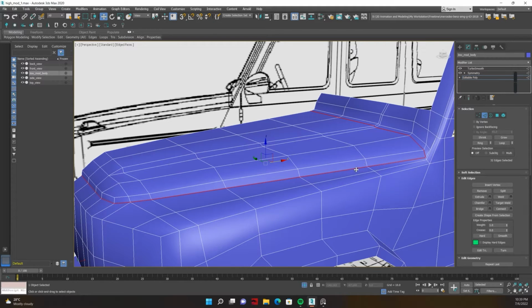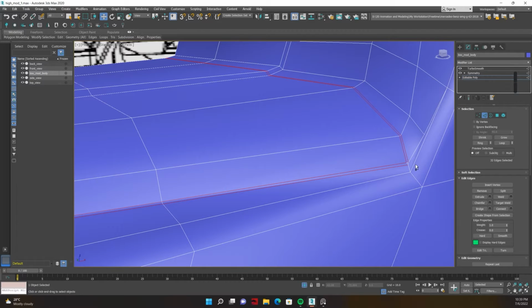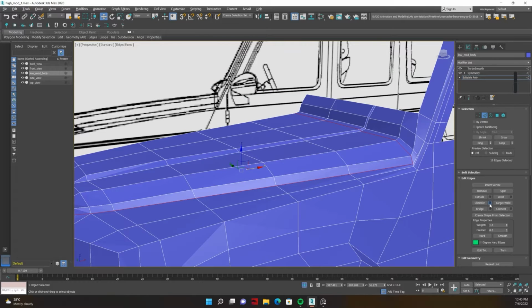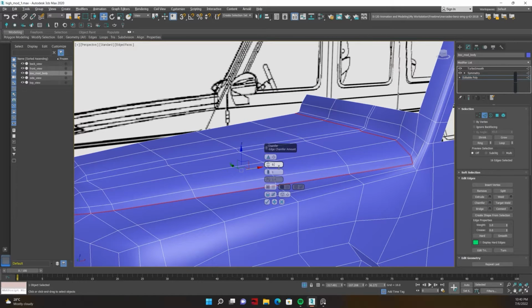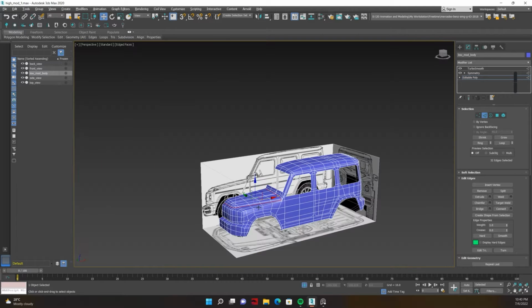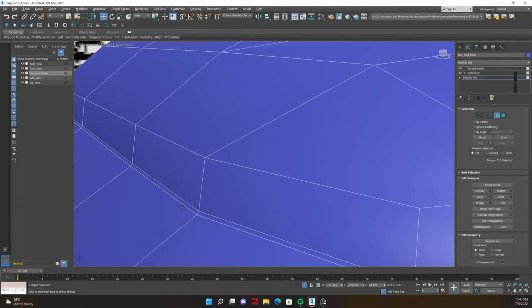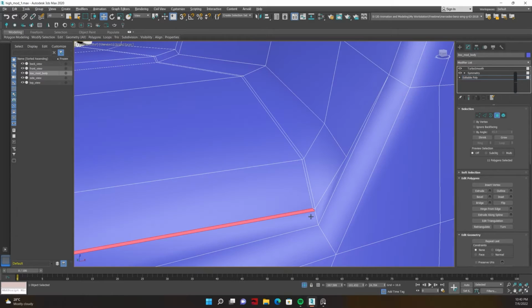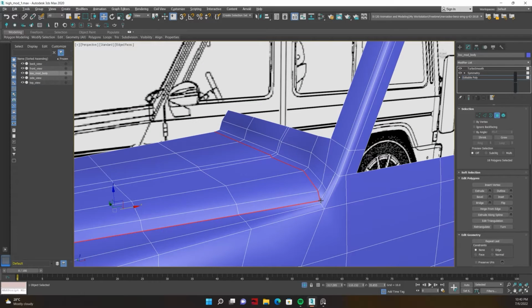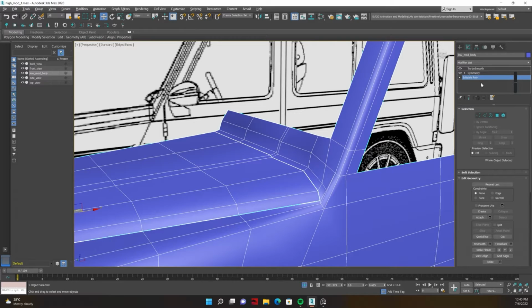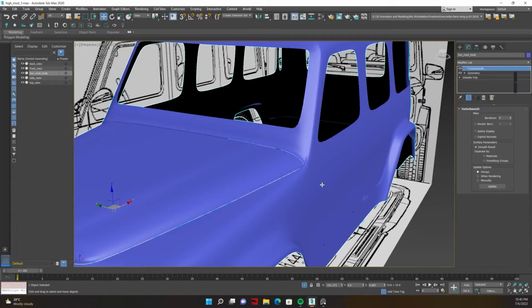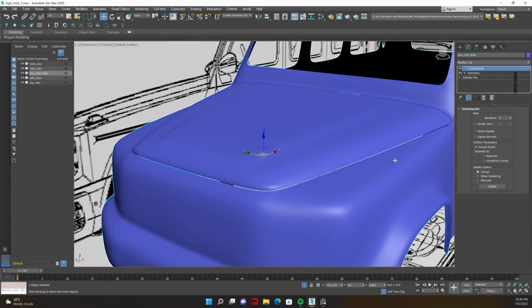I will move back to F4, and I will undo the chamfer things also, and I will just chamfer, and I will set this one to 0.2. Press OK. Again I will select the polygon selection tool, select this one, polygon selection tool, this one, and polygon selection tool. Delete, and okay, turbo smooth. It's okay for now.